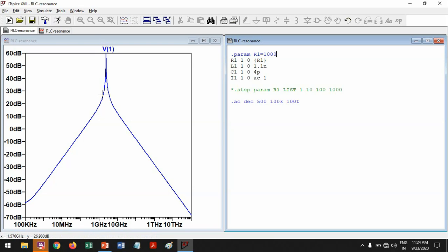Alright, it is a very narrow band pass filter, because it is allowing only a very narrow band of frequencies to pass through, and any frequencies around here it is attenuating significantly. Also notice that the slope of this line very close to omega naught is much higher than plus 20 dB or minus 20 dB. So that is a property of the function of omega that this is.